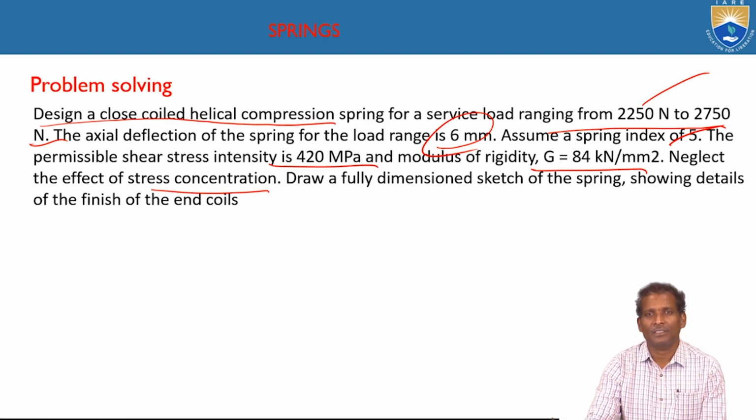If you consider stress concentration, what do you have to do? You have to multiply the stress concentration factors. Various factors are there: size factor, surface finish factor, reliability factor, temperature factor. All these factors affect the stress concentration, that is fatigue failure. So here there is no need, but if considering stress concentration, you definitely have to assume some factors.